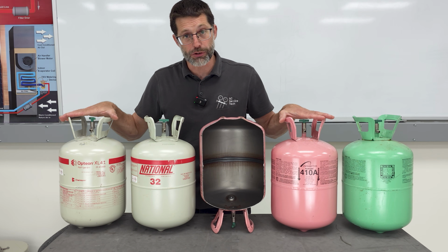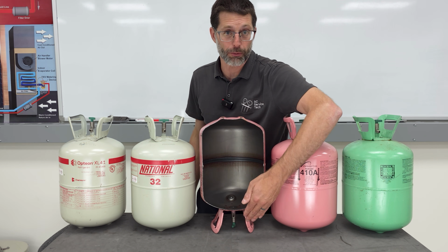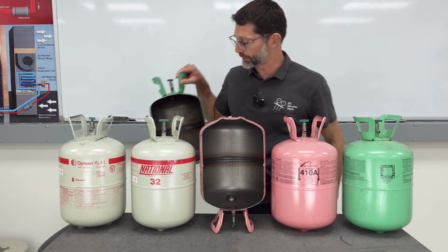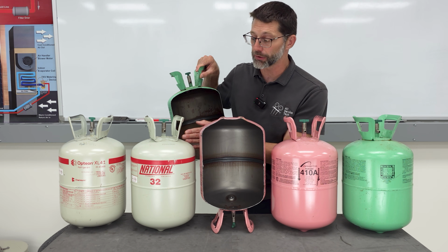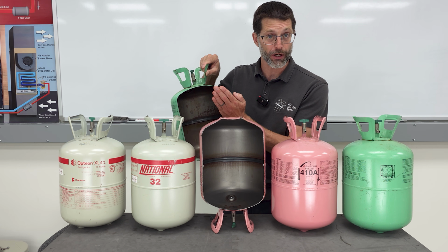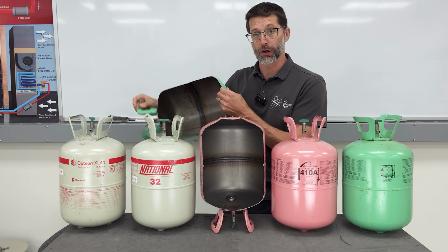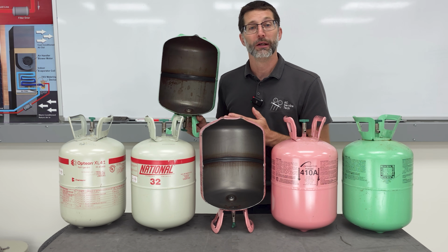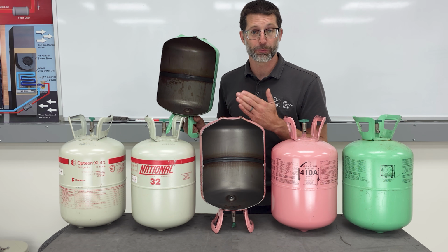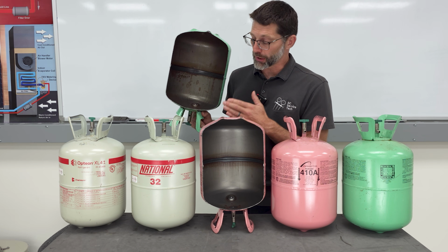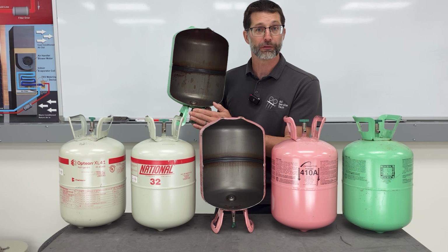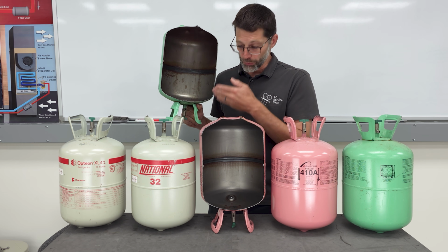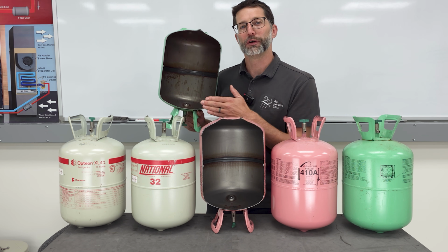Anytime you have a blend refrigerant, the refrigerant must exit the bottle as a liquid. So you have to flip this bottle upside down to charge with it. When you have a single component refrigerant such as R-22 or R-32, it can be charged as a vapor coming out of the bottle, or you could flip the bottle upside down and charge as a liquid. For instance, if you vacuum a system down, so it's an empty system, you've pressure tested it, you vacuumed it, you're going to break the vacuum with liquid refrigerant from the bottle, regardless of whether it's a single component or a blend refrigerant, in order to quickly charge the refrigerant into the system.